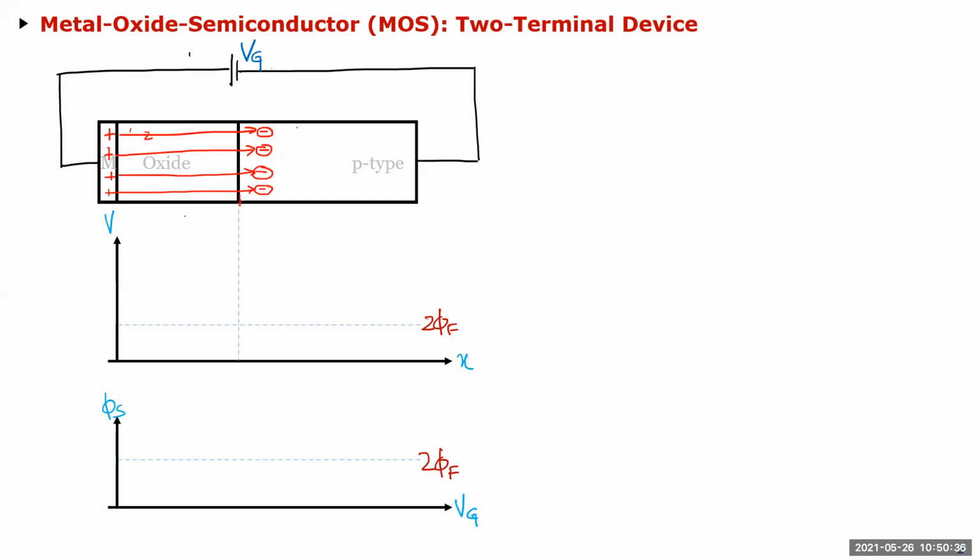Abhinav says, yes, sir, latch up, we get BJTs. Yeah, exactly. You get latch up because you get two BJTs back to back connected with a huge base resistance. So you get latch up in CMOS. We'll talk about latch up. We'll cover some of the advanced topics after we finish the inverter characteristics, and go into detail on some of this ancillary CMOS stuff. But the short answer is yes, BJT is still used, and there are a lot of applications.